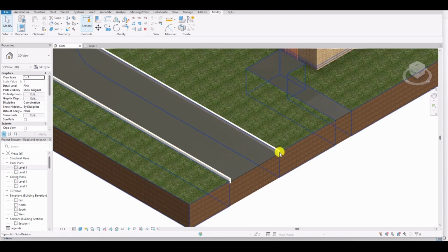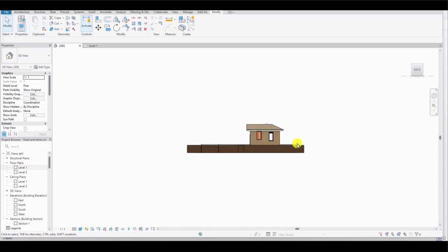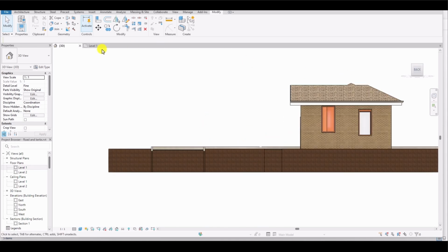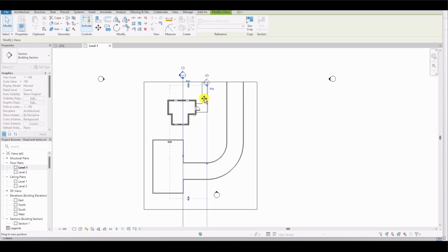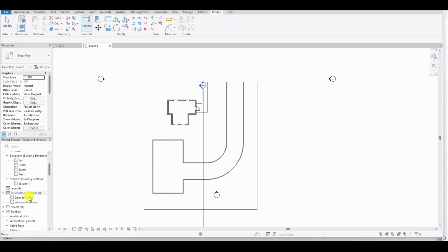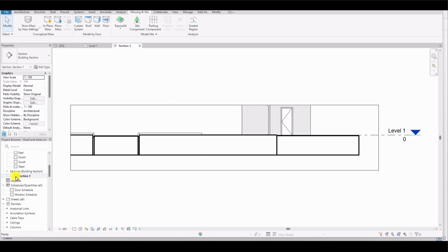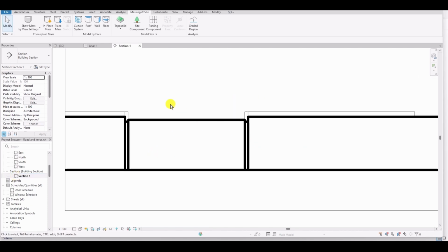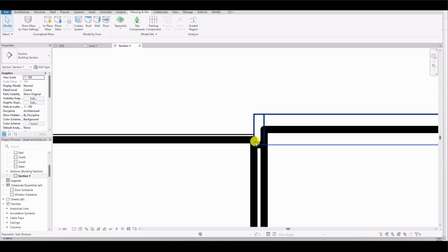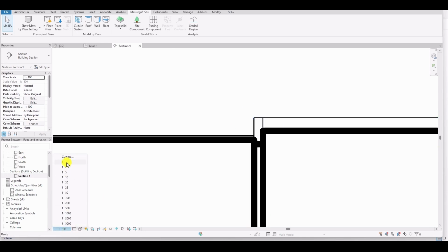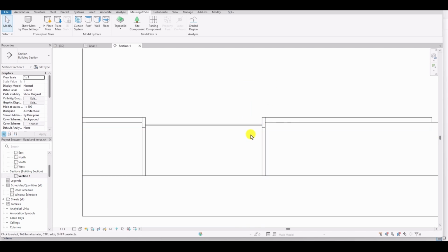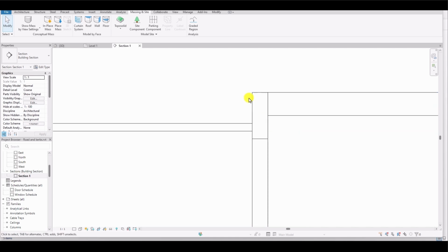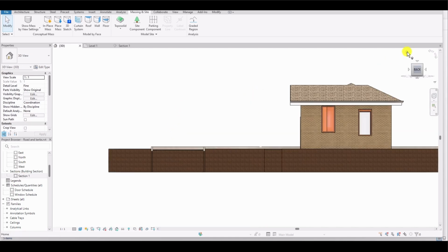This is one method of creating a simple curb. If you look at the cross-section of this curb, I have a section view ready. I'll change its position, then double-click on the section to view the road cross-section, including the curbs. I'll adjust the scale to make the lines clearer. As you can see, there's the curb, which is slightly embedded in the earth, along with the asphalt bitumen and the earth beneath the road and surrounding areas. Now back to the 3D model.